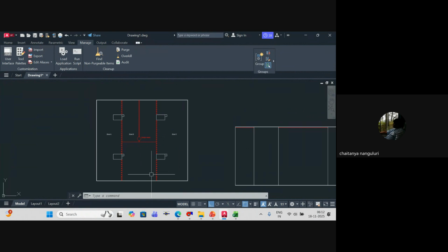So from the hydraulic calculation of the sprinkler, you already know at the starting point what pressure head you require. Then I'll add the static head, velocity head, and the frictional head. That's it for the remaining valves and all. But anyway, for HVAC, I have it. I'll try to get it for the sprinkler system as well. Let me see. I should have it. I'll just check it once. Okay, I'll try to share it. But do you want me to explain it, or is it not required?